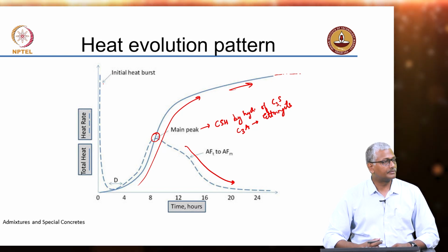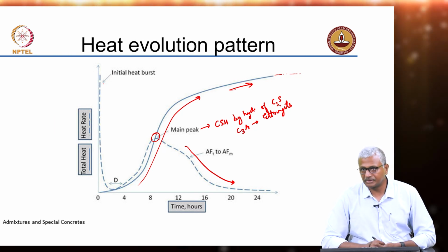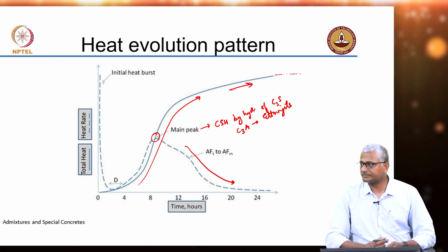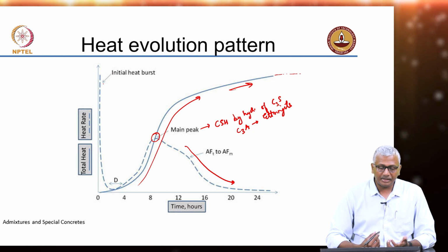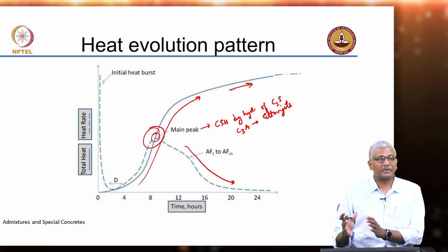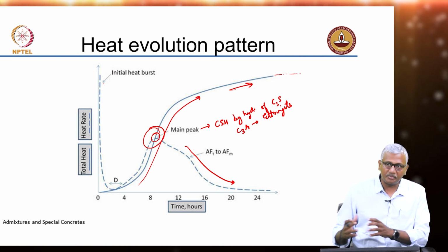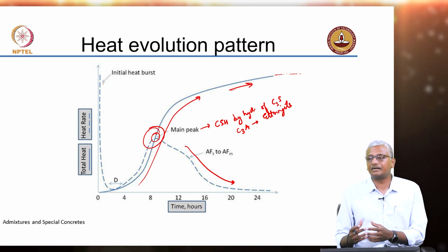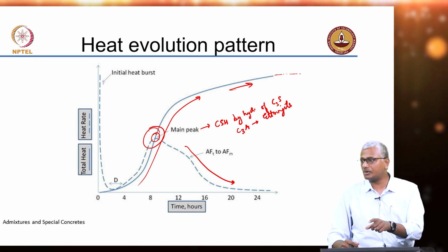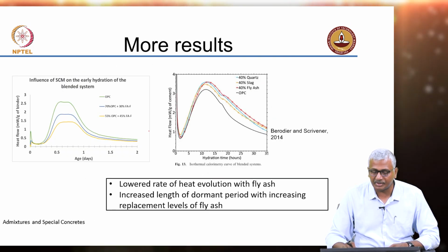The alumina reaction, which leads to the production of ettringite, will start dominating, and you may actually start seeing that this peak is getting clouded by too much alumina in the system. So, the alumina reaction starts dominating and prevents the silicate reaction from completely happening if you have too much reactive alumina. That is where you need to start worrying about sulphate optimization. I will talk about that in just 1 minute.